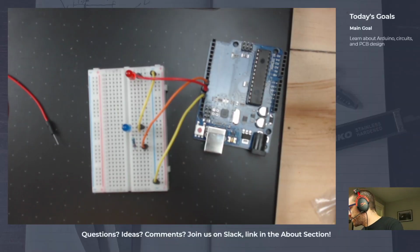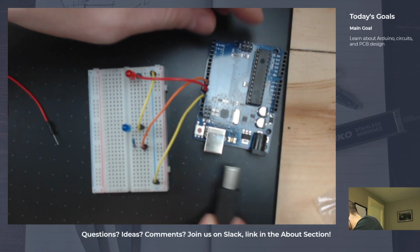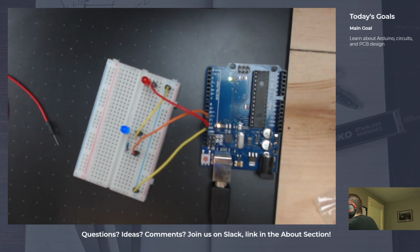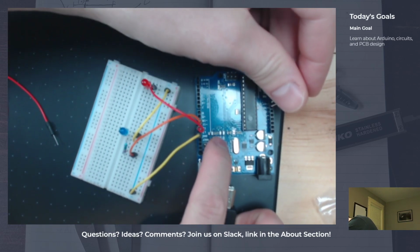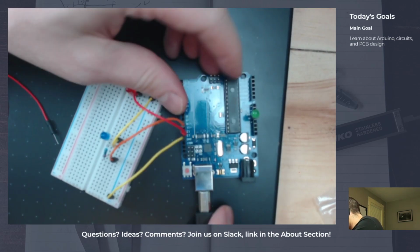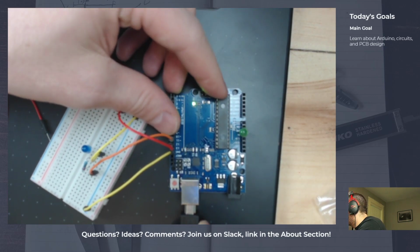Even I can demo it now, actually. But I'm going to put on my glasses for that. Should have my glasses on anyway. Safety first. Okay. Well, actually, we'll just demo this real quick. So you can run an LED directly between 5 volts and ground. Actually, let's unplug this before we do it. So I'll plug one side into 5 volts, the other side into ground. So if we watch this LED, it's going to turn on and then immediately pop and burn out. That was it. It's already over.